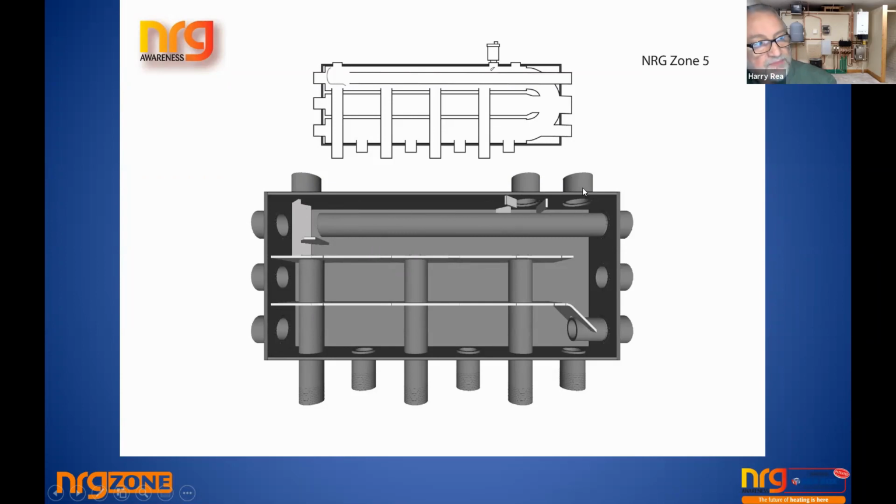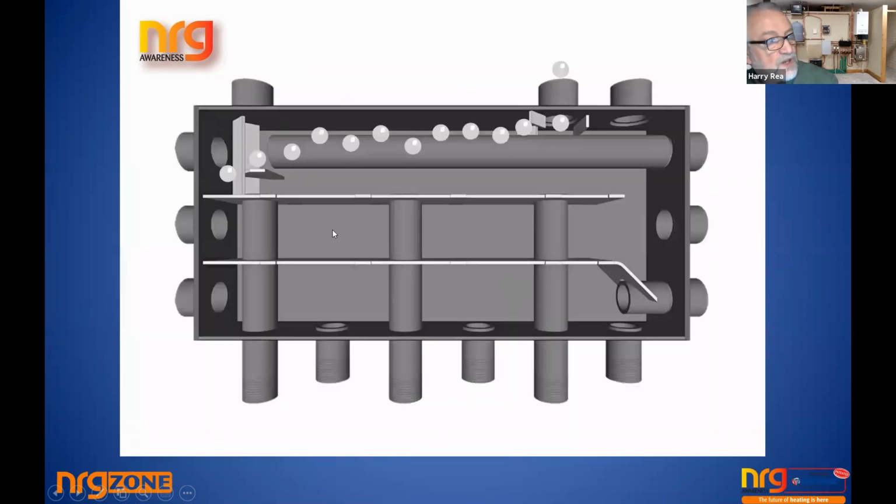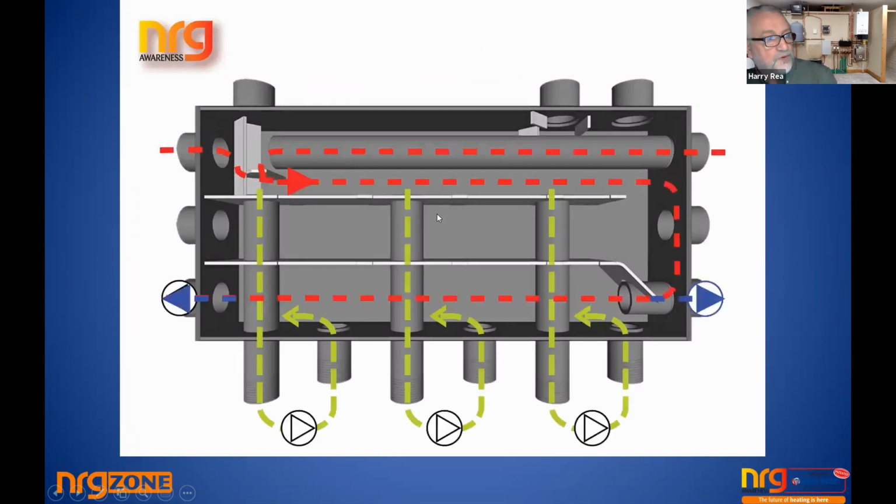Again, if a cold feed is brought in here, it's down into the system neutral point. And so if you had a condensing boiler, it could come down here. It does not mean that you couldn't put a condensing boiler here, because this is perfectly open to that chamber. So if you had a boiler, you could put the return here, and there's reasons why you would do that. We'll look at it in a while. So again, you can see the idea. The air coming in from either pipe drifts along and goes off out the return.